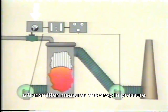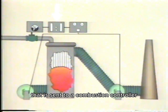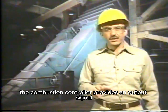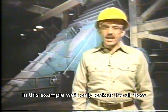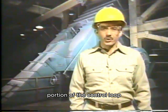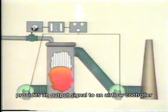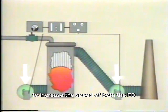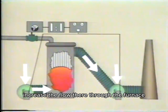A transmitter measures the drop in pressure and converts it to a signal that is sent to a combustion controller. The combustion controller provides an output signal to control both fuel flow and airflow. In this example, we'll only look at the airflow portion of the control loop. The combustion controller provides an output signal to an airflow controller, which produces a signal to increase the speed of both the FD and ID fans, and as a result, increase the flow of air through the furnace.